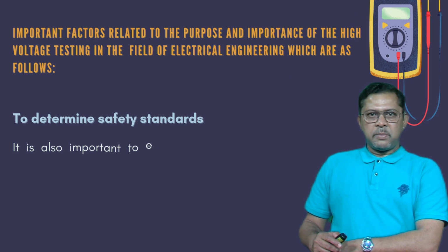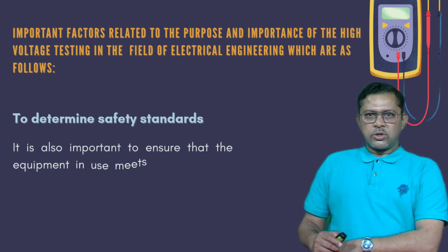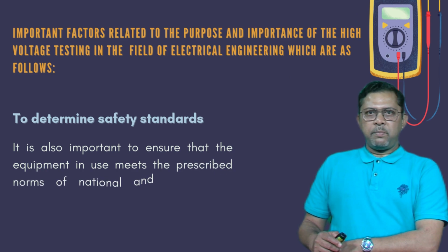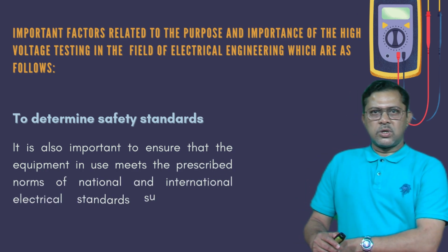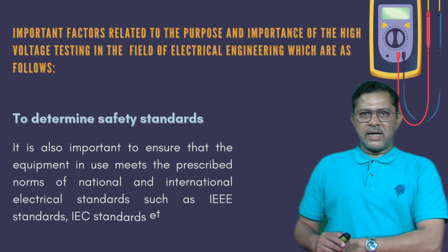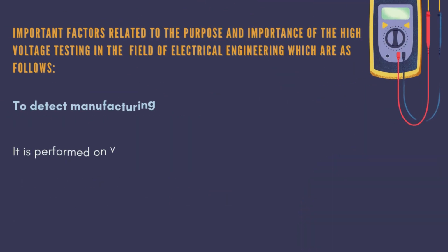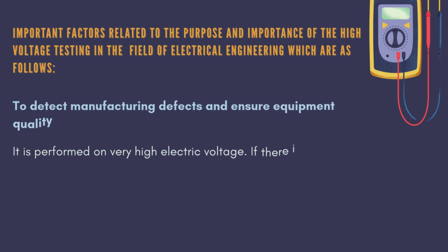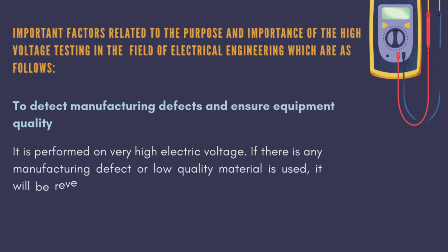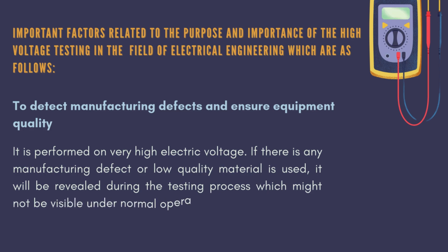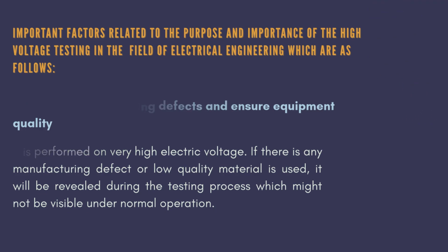Third is to determine safety standards. It is also important to ensure that the equipment in use meets the prescribed norms of national and international electrical standards such as IEEE standards, IEC standards, etc. Fourth, to detect manufacturing defects and to ensure equipment quality. It is performed on very high electric voltage. If there is any manufacturing defect or low quality material is used, it will be revealed during the testing process, which might not be visible under normal operation.